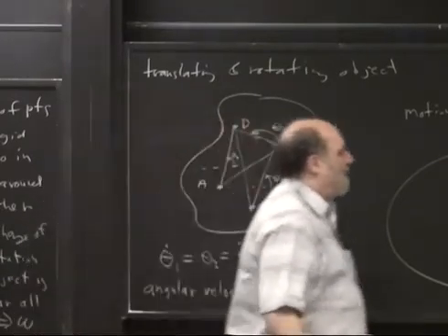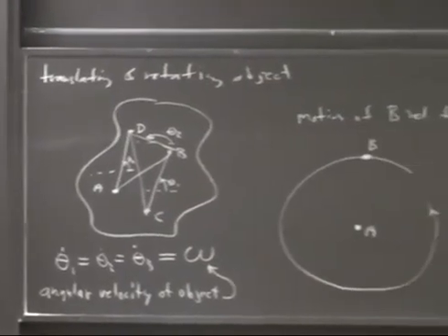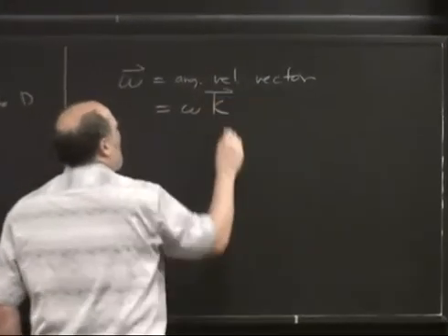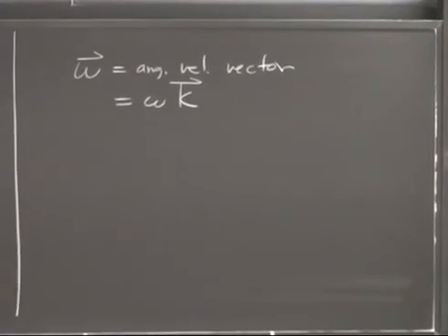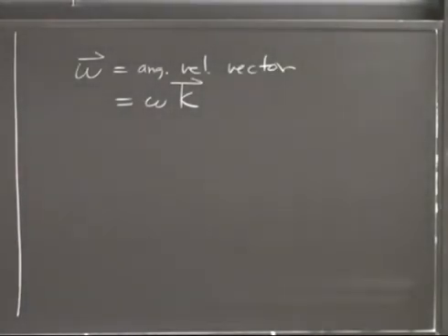And you can write it as a scalar like that, or we can write it like this and call this the angular velocity vector. And the reason we might want to think of it as a vector is, one, someday we might take a three-dimensional course, and in the three-dimensional course we have to think of angular velocity as a vector. And two is, as a vector we can use formulas that have cross products in them that give us reasonable answers. Just like in planar motion we have i, j, and k sticking out, sometimes it's useful to think, for example, that e_theta is k cross e_r. So it's useful to use that cross product with k even in a two-dimensional problem.